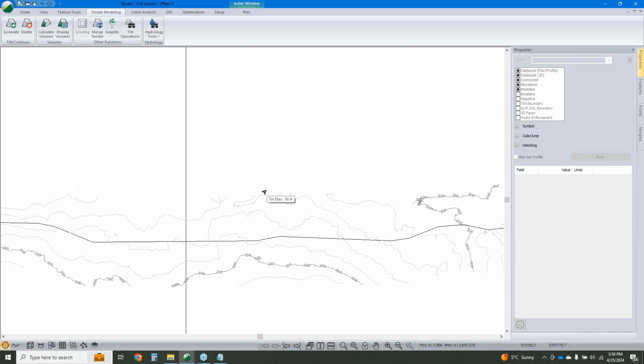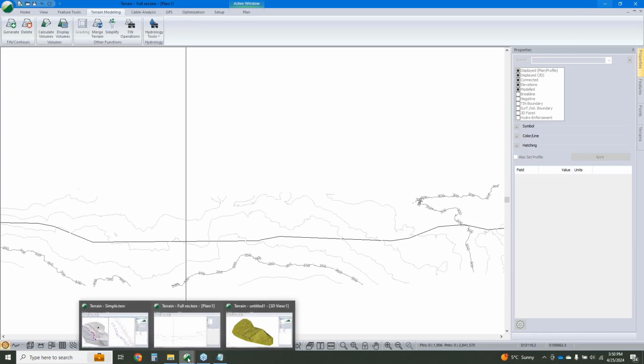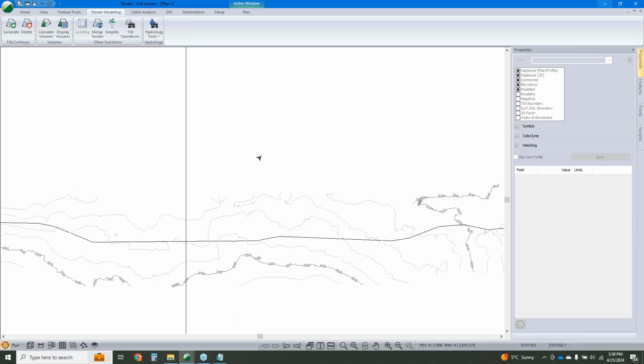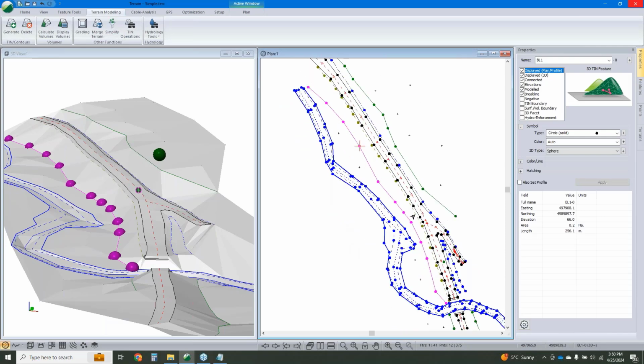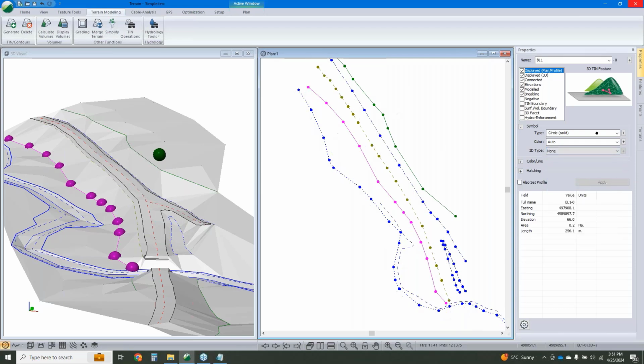Awesome. Okay, let's do a couple more. The next question, actually, looks to be two kind of in the same space. The first one says, my surface has triangles outside of my project. How can I correct that? And the other question that appears tied to it is, what is maximum triangle side length? All right, yeah, those people must be talking to one another because they definitely go hand in hand.